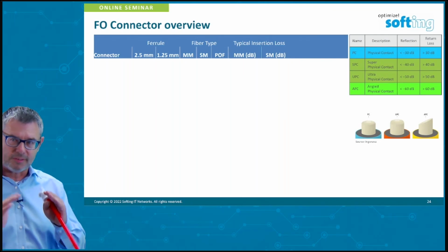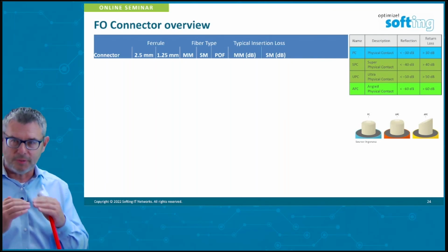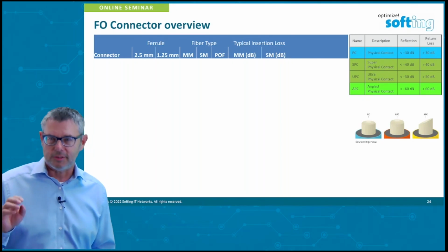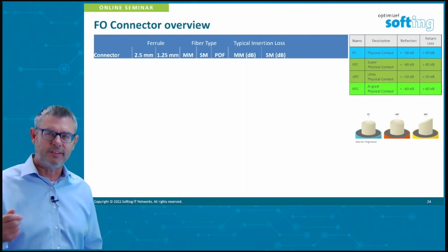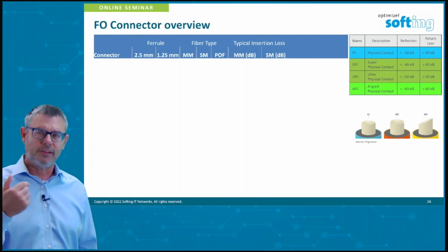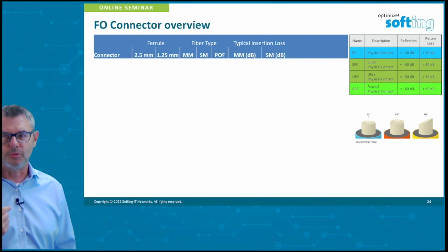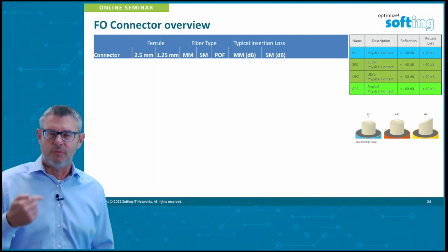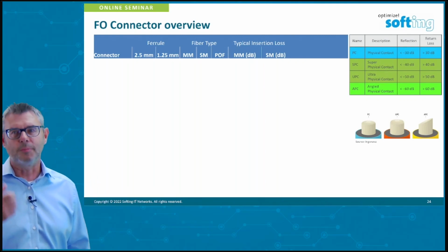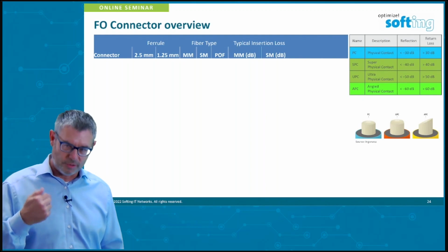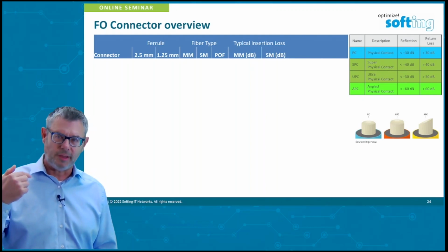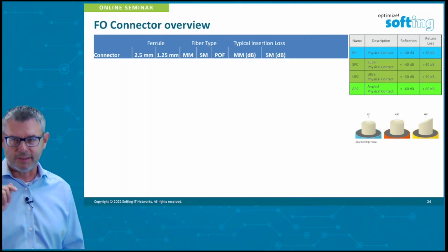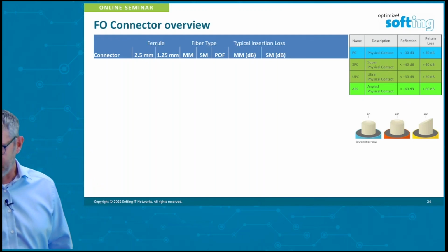This minimizes the area of contact and optimizes them, and you see this in a few parameters, like the reflection, how much light is transmitted directly back to the transmitter. It is important to keep that number very low, so as not to have too much energy sent directly back to the transmitter. We want the light sent through the cable.